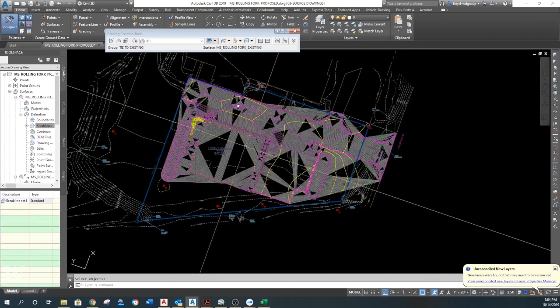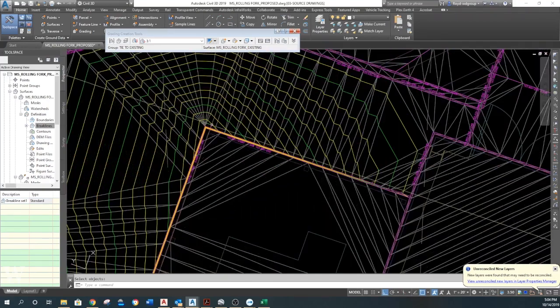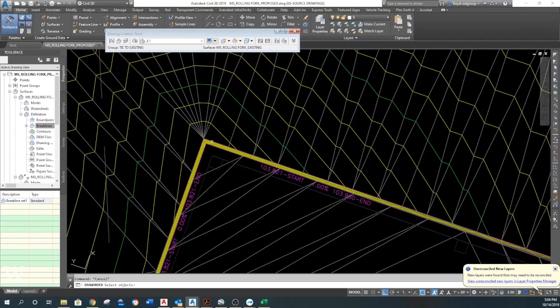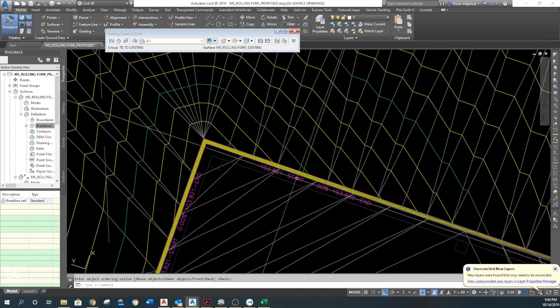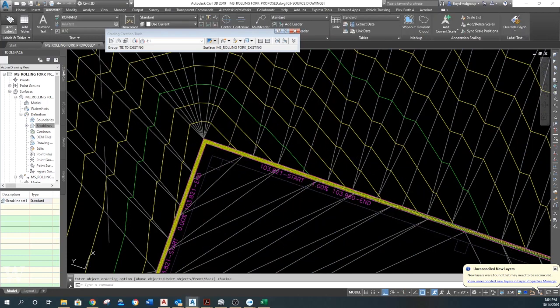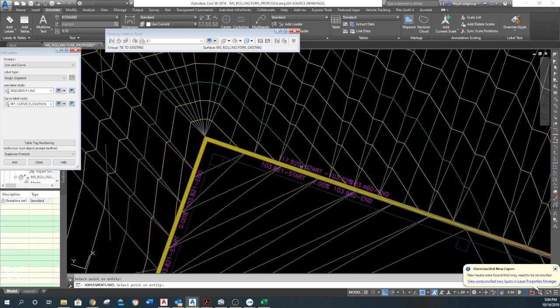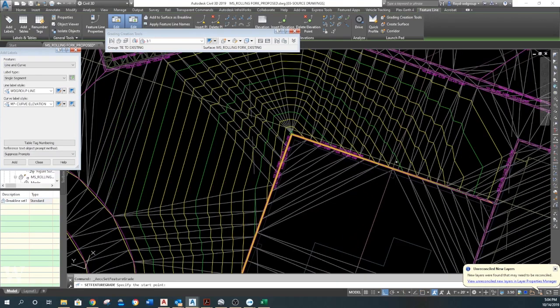and voila, I have a bad spot. How do I know I have a bad spot? I got a bunch of contours right here, so I forgot to assign something an elevation right there. I just don't know what. So let's do some quick annotating. Line. We add a quick annotating right here. That's it right there. 117.925. Okay, that should have been the easiest way to do that, because that's a long line.